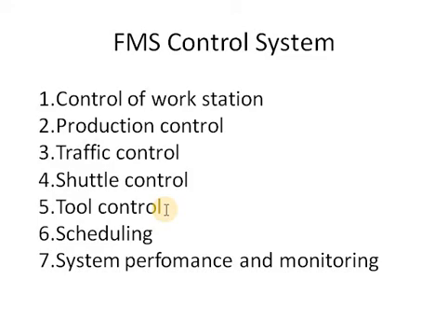A file is maintained on the machining time usage of each tool. When the tools are located in the tool magazine, the accepted tool life is entered in the control memory along with all other tool-related information, such as offsets. As the machining process proceeds with various work parts, the controller records the actual time for which each tool is used. When the cumulative machining time reaches the life for a given tool, the computer notifies that a replacement is in order. That is what tool control is.